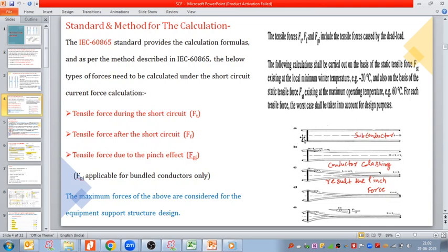Two run. Like you can see over here, if it is clear, A and B. So in one phase, I am using two conductors. Why am I using two conductors? To support the continuous current and to support the short circuit current, right? As we have done the bus bar sizing calculation in module 4, about the conductor selection, we have discussed whether we require single conductor or twin conductor. So twin conductor means two conductors per phase.